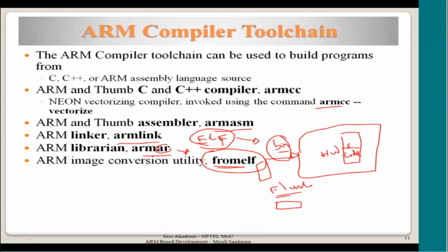The image may say that at this particular address, a particular binary, that is the code, all the assembly instructions encoded into a 32-bit format. It will give the address and then the content. So it may be expressed in some particular format, so that wherever it is mapped in the flash device, in that location it has to be put. So flashing is a time consuming job.